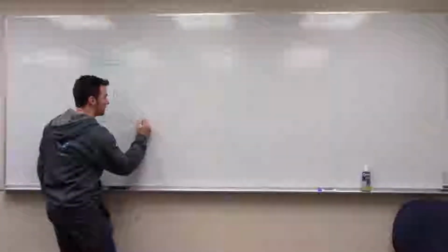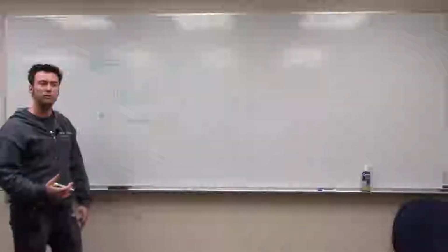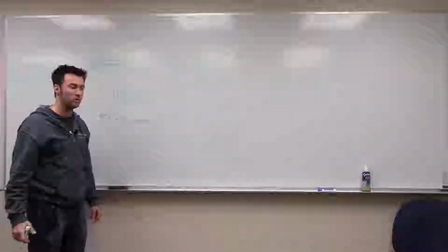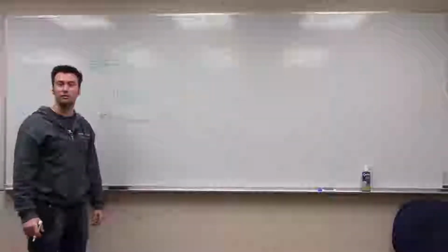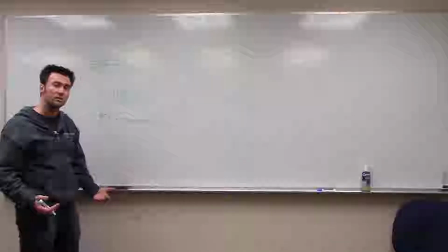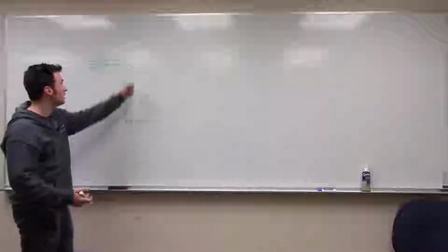So minus c x dot is equal to mass times acceleration, right? The sum of the forces on a system is equal to the mass times the acceleration of the center of mass of the system. That's what Newton's second law says. And in this case, the acceleration is x double dot, the second time derivative of my position variable x. So m x double dot.